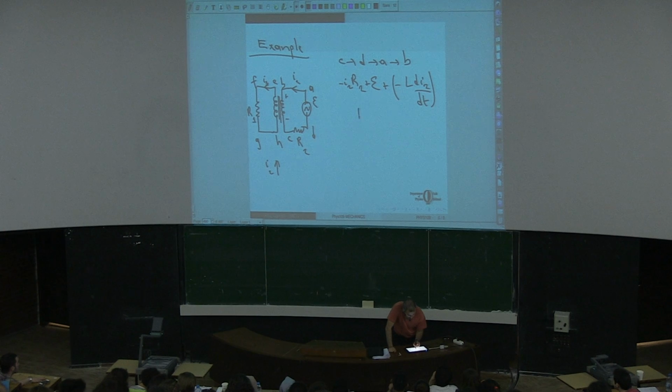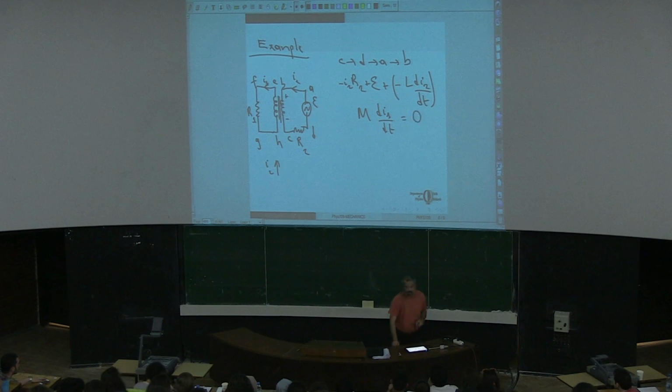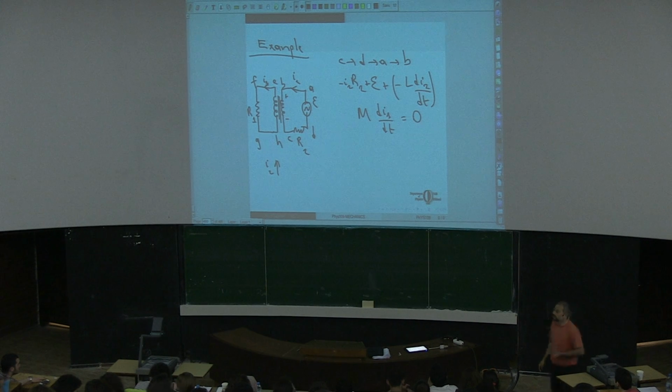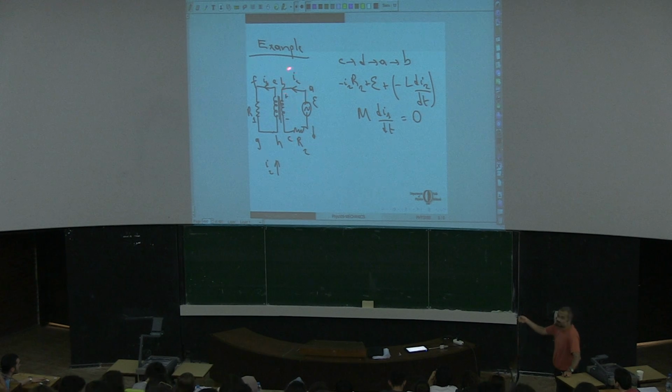And that EMF will be M di1 by dt. Now the problem is, will it be positive or negative? Well, it will depend on how you connect these wires. If you would connect it in one direction, it will be a positive sign. If you would just change the circuitry so that you connect this wire to this terminal and this wire to the top terminal,